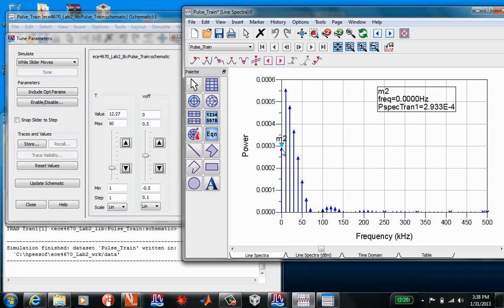It's supposed to nominally be whatever the average value of the waveform is. And these guys are doubled because I'm folding the negative spectrum to the positive. Does that make sense? Mm-hmm. It looks to me like if these were halved, if that one right here was brought down to here, they'd be sitting kind of like you'd expect them to look for the two-sided. ADS doesn't do that because ADS is trying to emulate lab equipment. So they're trying to make this look like what you'd measure in the lab off a spectrum analyzer.